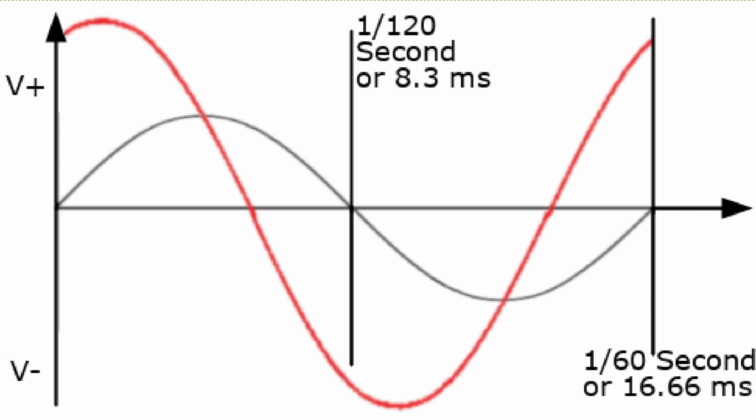So if we were trying to see the voltage between the neutral and the high leg, let's see how far apart the two sine waves are, and let's see if we can see a pattern. You can see here the two sine waves cross, and so there's no voltage between them. But as we go along, they're growing further and further apart. And down in about here, if we're looking at this with a ruler, we can see that right about here is where they're about the furthest apart, vertically speaking. But then as we get past that point, they start getting closer and closer together, until again we reach right here where there's 0 distance between them, and so on.